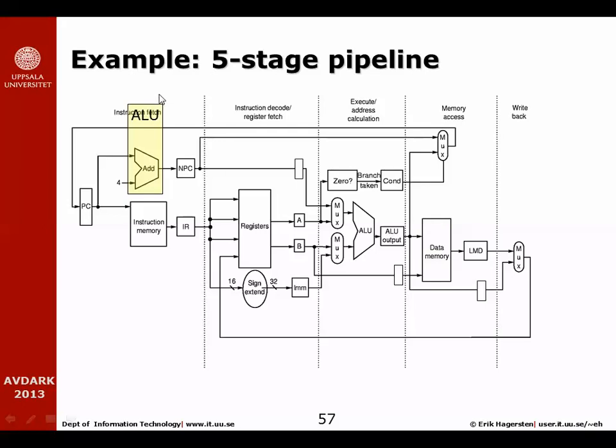Up in the top left corner is another ALU, and this ALU is connected to the PC. It has a specialized job: to always add 4 to the program counter. That assumes here that we have an instruction of 4 bytes. So every time we execute an instruction, we need to increment the value of the program counter. So these are our main characters of this movie. Let's see how they work together.